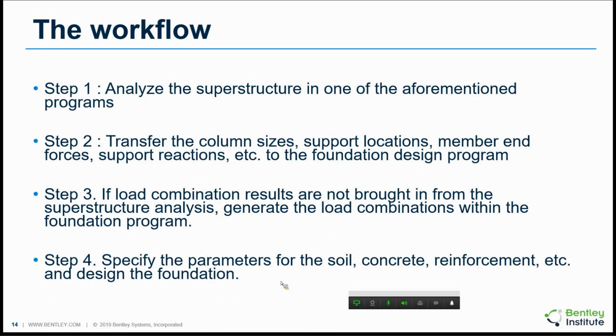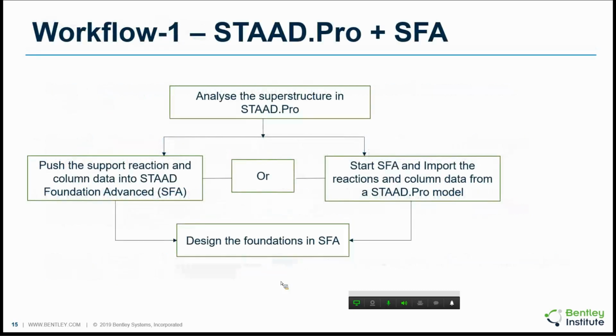Once the load combinations for the foundation design are generated, you go on to specify the parameters for the soil, concrete, the reinforcement, etc., and perform the design of the foundation. So this is the workflow in broad terms. In this presentation, I will show you 4 of those workflows.